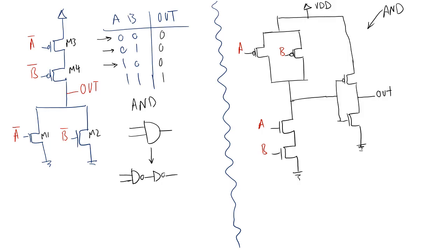It's not the obvious answer, so I would encourage you to pause the video, try to think about it, and then come back and resume the video, and see if you guessed it right. Okay. So the idea is really coming from the number of transistors used. The answer is basically the number of transistors. So here, for the circuit on the right, I have 4 transistors for the NAND and 2 transistors for an inverter.